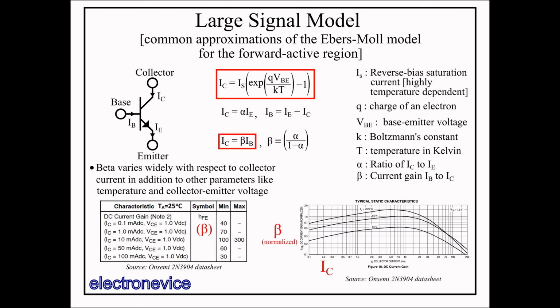So these are our two central equations that govern the operation of BJTs. We have an expression for IC in terms of VBE, and an expression for IC in terms of IB. With these equations, we can set VBE to a value, and we can determine IC, IE, and IB from that. The only circuit parameter we're missing is the collector voltage.